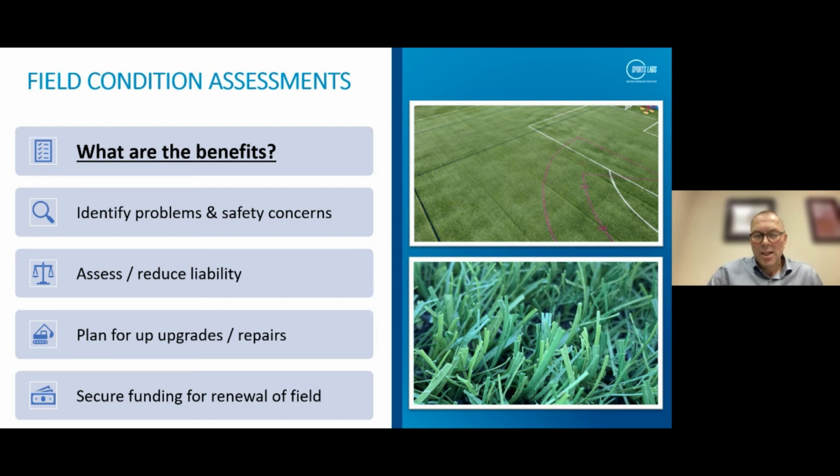Yeah, I think you dial in maintenance based on the manufacturer's recommendations. The supplier of the turf has very formal maintenance recommendations, and that's what you've really got to follow to protect your warranty. But then the number of hours of use that the field is experiencing may mean that the frequency has to be increased, or the type of equipment or the intervention that's used has to change. Decompaction and moving infill around can be major issues.